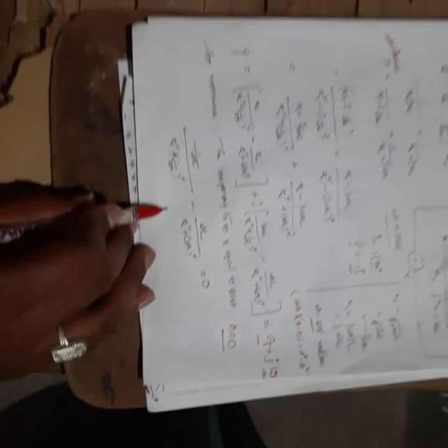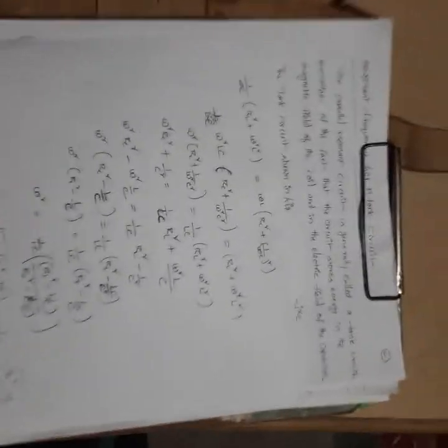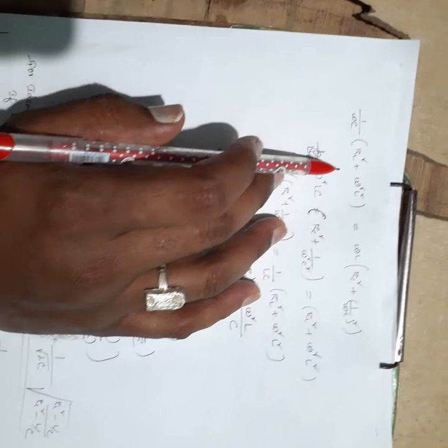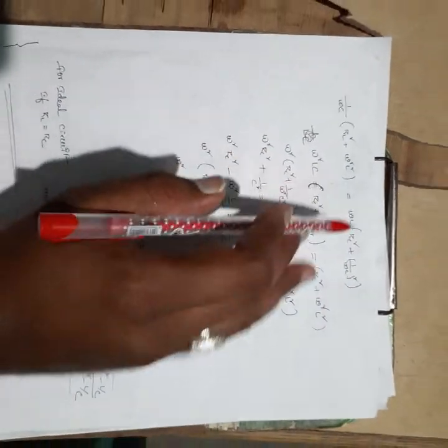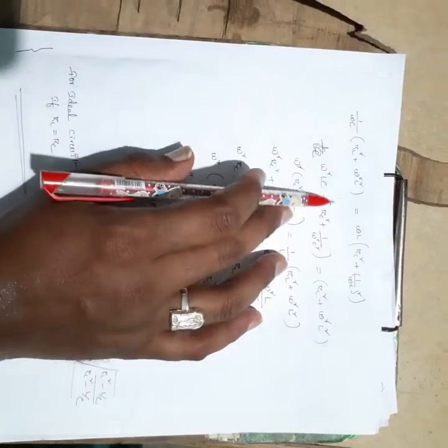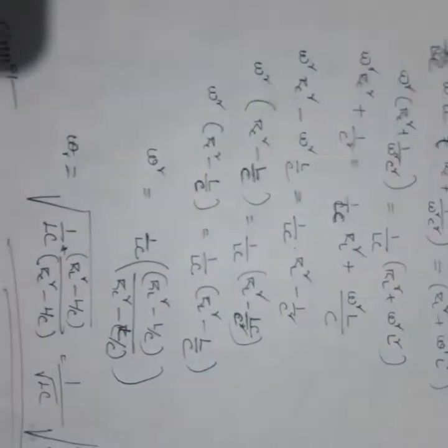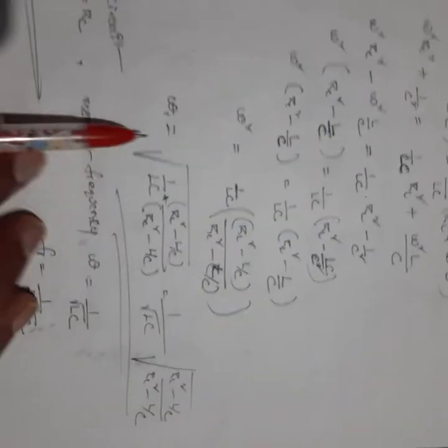So this is what I am getting. From this I am simplifying the circuit and calculating the equation. So 1 by omega C = (R_L square plus omega square L square). Here omega is nothing but angular frequency, so that is the resonant frequency. That's why I'm writing omega r at the last end.